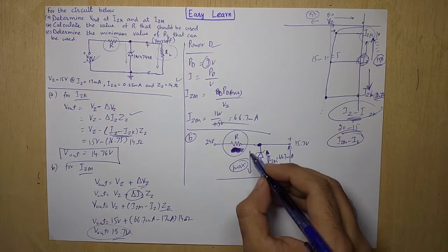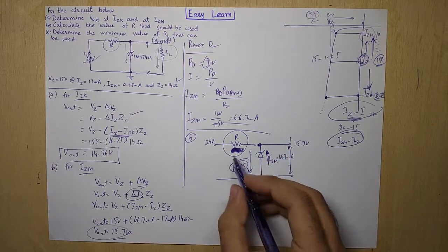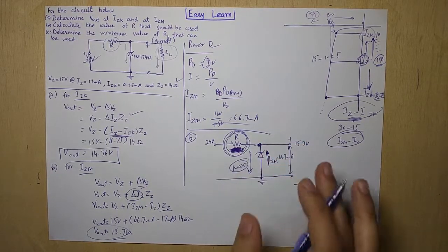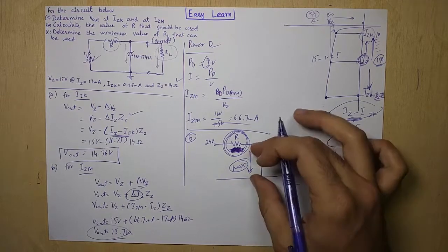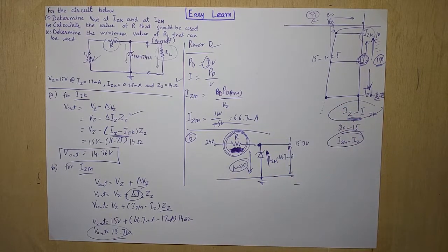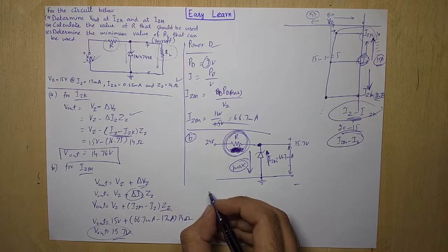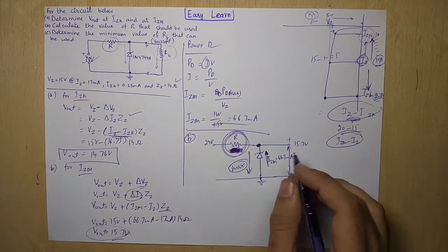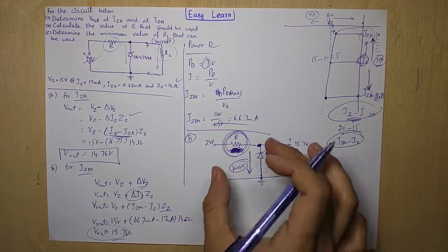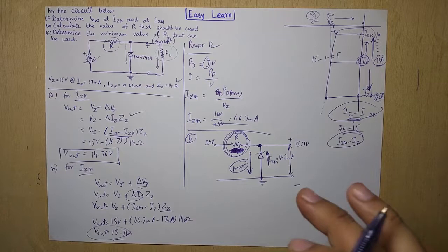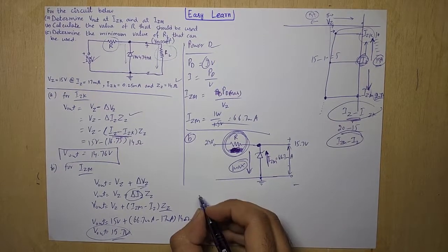But in the situation in which the maximum current flows, protection is necessary. Because we want to protect our Zener diode so that it will not burn out, a limiting resistance is necessary. So we want to calculate the limiting resistance, and whenever you are calculating the limiting resistance, you have to focus on the maximum rating of your circuit. Okay, this is a point.